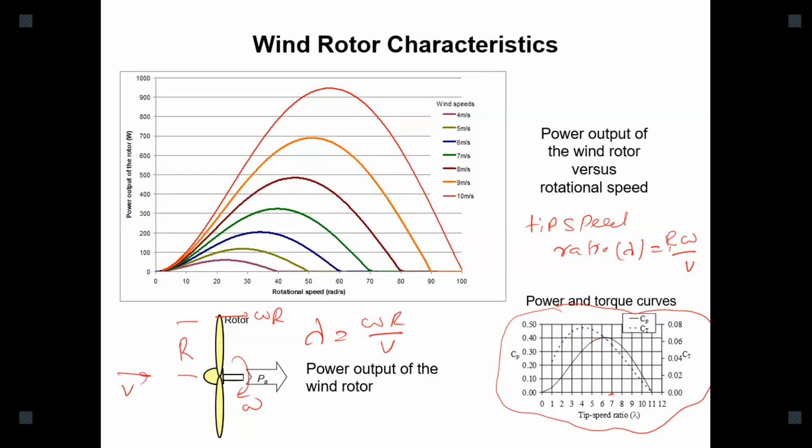What I explained previously: if the tip speed ratio is less than 7, we cannot maintain that 1/3 ratio between upstream and downstream wind speed. Then we need to maintain the tip speed ratio at 7 to maintain the upstream and downstream wind speed exactly. Only at that point does this wind rotor absorb the maximum possible energy from the wind. Then actually we can generate this curve, obviously.